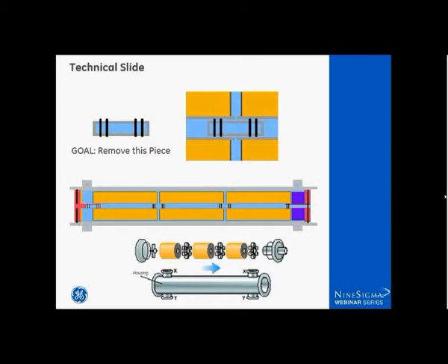And so the goal is to connect those 2 tubes and remove that interconnector with those 2 O-rings. Now, your solution may include an O-ring, it may include some other type of sealing mechanism, but it has to withstand the operating pressure of reverse osmosis, which is approximately anywhere from 100 to 300 psi in the outside of that housing. And one reason that O-rings are used is because if you set up the tolerance, their compression is very good at sealing. Your design has to incorporate that same sort of ability to seal from the high operating pressure reverse osmosis and prevent leakage of the dirty water into the clean water inside that tube.